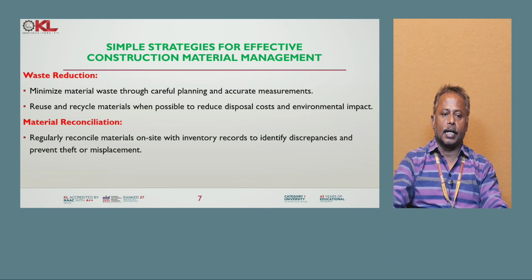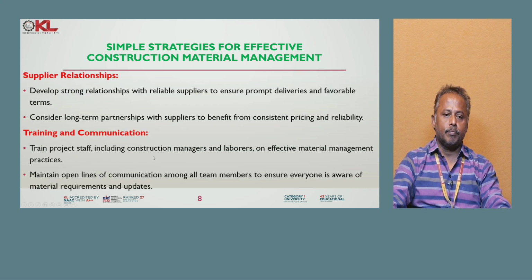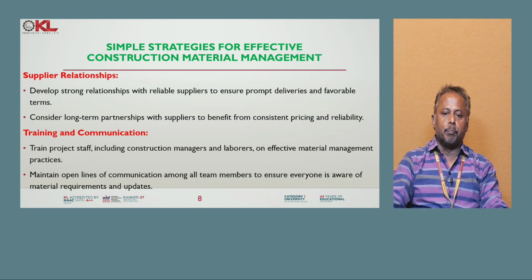Next, material reconciliation. Regularly reconcile the materials on site with the inventory records to identify discrepancies and to prevent theft or misplacement.